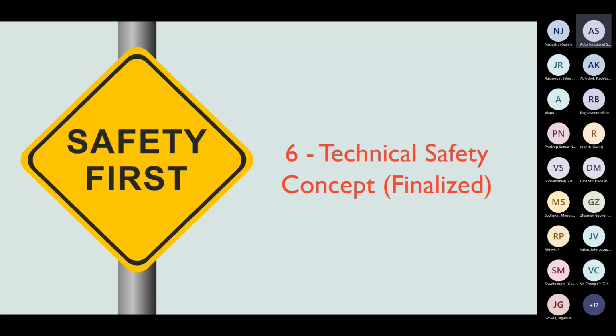To achieve sufficient mitigation of the systematic failures, we have to follow all the methods stated in the process according to the different SL levels, and the processes increase more and more as we go to the higher SL levels. That is how we take more and more stringent measures to mitigate the systematic faults. So the answer is that we need to consider both the systematic fault mitigation as well as the mitigation of random hardware failures to call a system SL compliant.